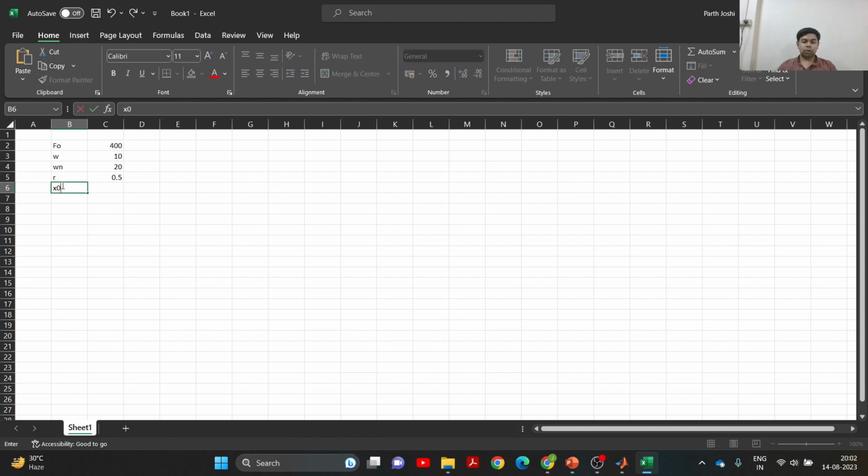So we know x naught is 0.1 and the initial velocity is 0. So therefore A is x naught, which is 0.1, and B is basically zeta omega n A upon omega d.